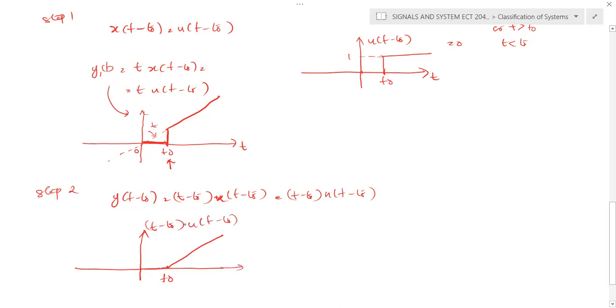So see the difference. Here you can see the signal shape. The two outputs are different. So the same problem I just explained in a graphical way to get a clear idea. Okay, this is actually the time invariance concept. Here you can see that if both signals start from t0 onwards, or both signal shapes are the same, we can call it a time invariant system.